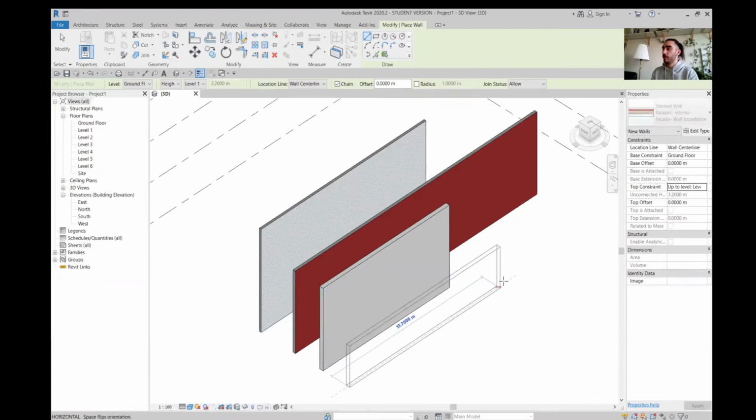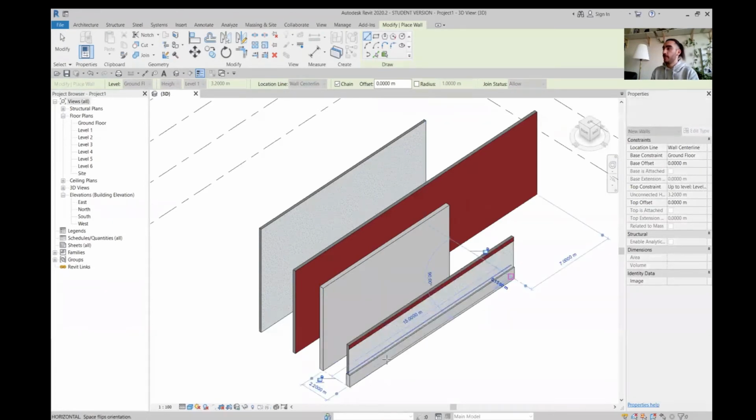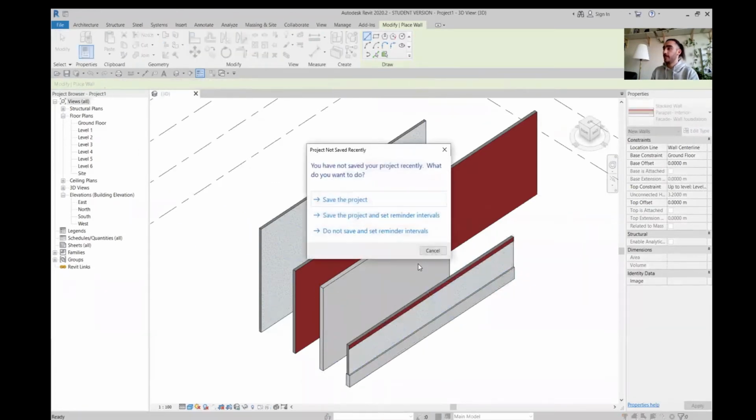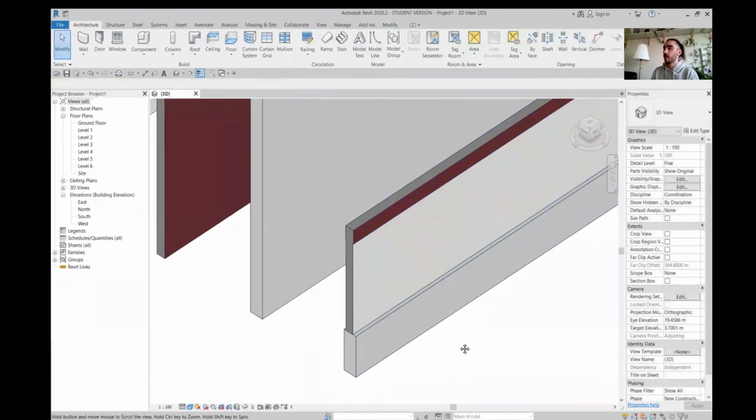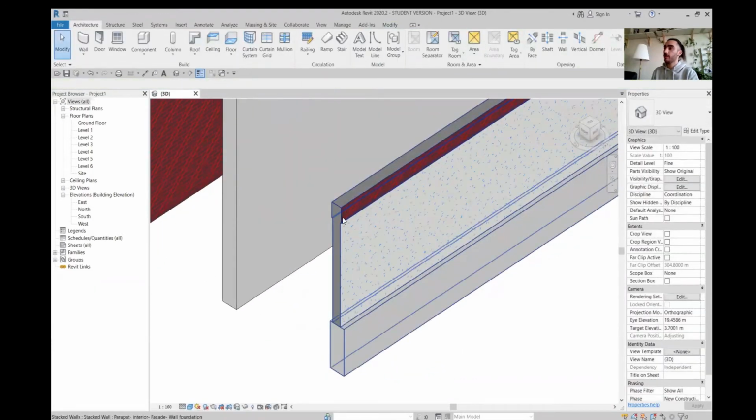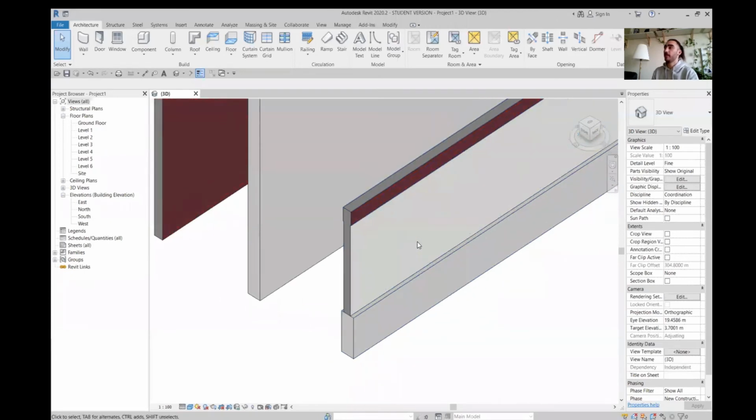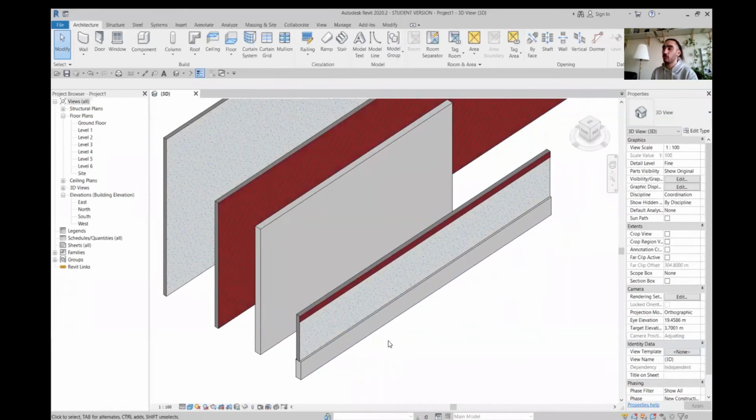So what I can do is to super easily create my stacked wall here. As you can see, the parapet wall is only getting assigned with almost around 30 centimeters. So imagine the roof will happen from here, and then up from the roof, we're having no longer the gypsum material on, and it's all brick. So that's the way how you're supposed to technically design and set up these stacked walls. Super easy and super simple.